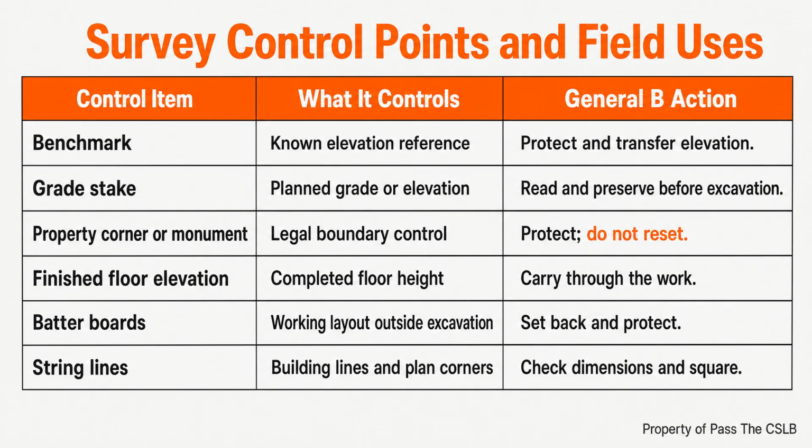Survey monuments deserve a higher level of caution because they can be part of the legal record of property boundaries or subdivisions. When construction threatens to disturb an existing monument, California law requires the monument to be located and referenced by a licensed land surveyor or authorized civil engineer before the disturbance.